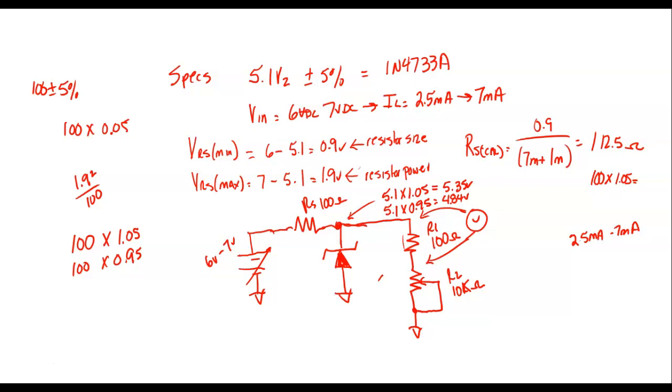Calculated. It's calculated is what it is. And these Zener power supplies will never use that resistance exactly. It'll give us a starting point where we can come in. But what you always want is for the current to move away from that knee. So what we did is we calculated what resistor would put it right here. So if something happens and it goes up into here, then it goes out of regulation. So what we want to do is put more Zener current in there, right? Understand?